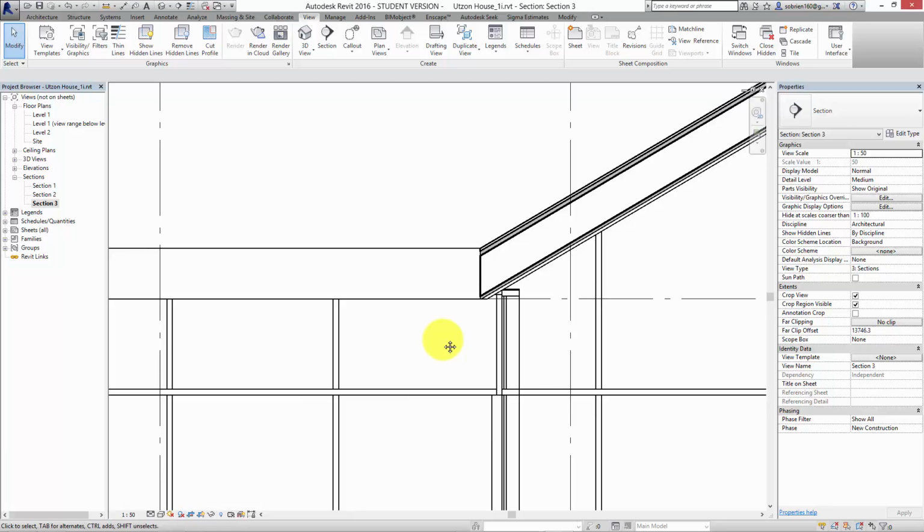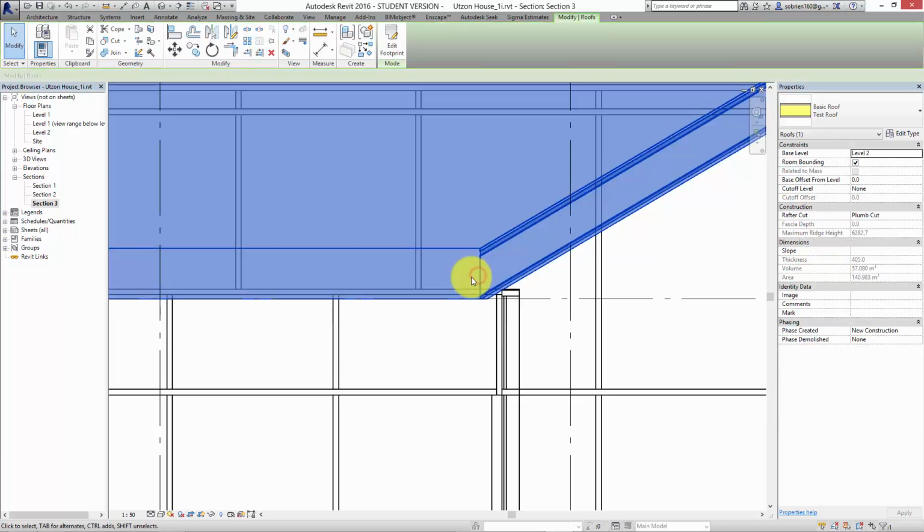Because if you just put a big fat end of a roof on something and you slap a big plastic fascia board on it, it just looks like shit. And that happens all over the world, and it looks like shit. It doesn't matter how many times you do it, it still looks like shit. So what you need to do is control the thickness of the fascia.